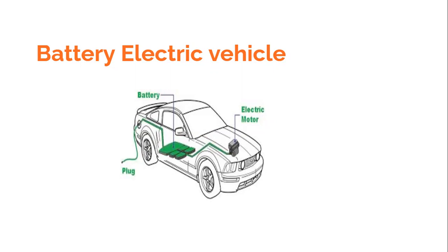Once depleted, we need to charge this battery pack, and it takes a lot of time as compared to refueling a conventional IC engine vehicle. It could be as long as 36 hours to replenish the batteries. If you have a charger and a supply with 230 volt AC in your homes or offices, it might take you around 10 hours to fully charge this battery electric vehicle by plugging your car into the supply. So you see a plug over here which can be used to plug in, and it takes about 10 hours for fully charging. So this obviously is a bit time consuming.